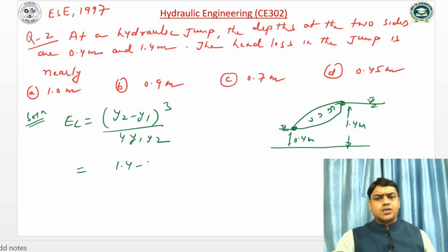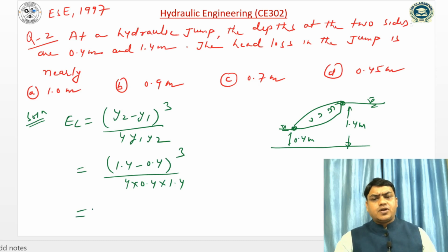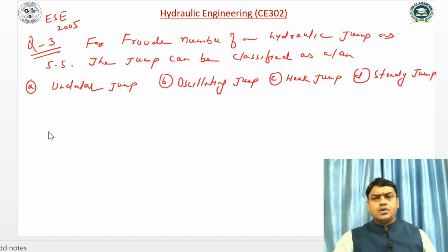So (1.4 minus 0.4) whole cube divided by 4 into 0.4 into 1.4. So energy loss will be 1 divided by 4 into 0.4 into 1.4. So it will be 0.45 meter. So D option is correct. For Froude number of a hydraulic jump as 5.5, the jump can be classified as...